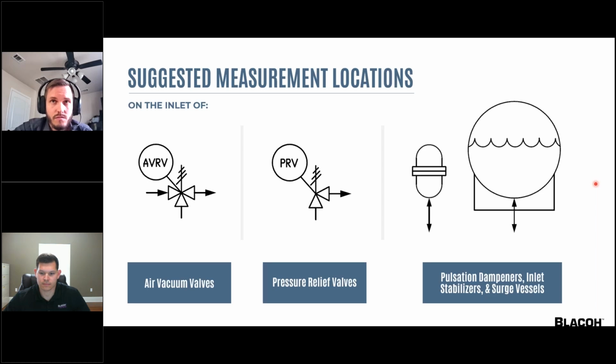If it's used with another pressure device on the air side, the differential pressure will tell you the liquid level, which for bladder vessels tells you whether the bladder is positioned safely. It can verify the performance of the dampener by measuring residual pump pulse. You can tell whether the vessel sizing is correct when intentional pump trips and valve closures are performed.